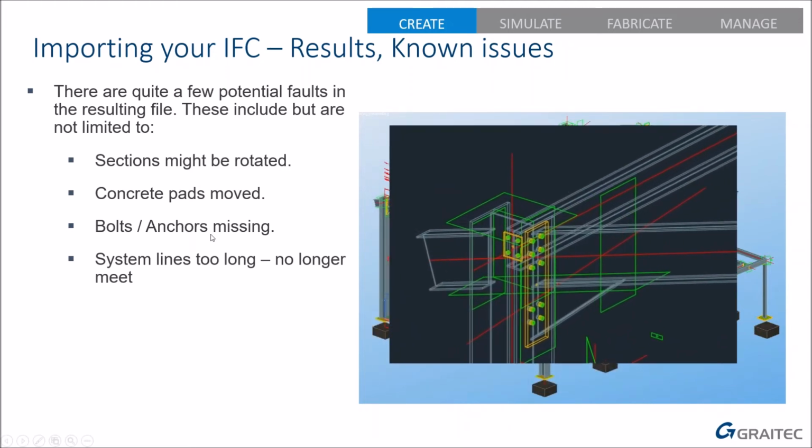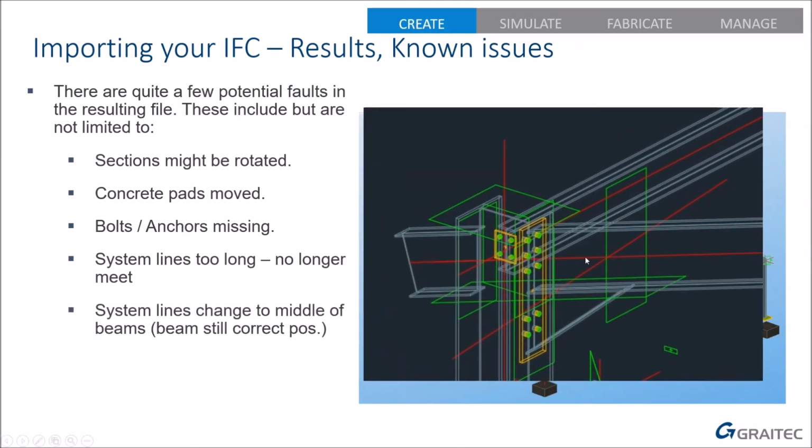And actually, if you go into 2D wireframe, you can see they've also moved the system lines. The beams are in the right place. I have checked. They're in exactly the right place, but the system line is no longer top middle for the horizontal beam or the rafter. The system line has been moved to the middle. And that's no good because when you're doing your drawing and your dimensioning, it's important to have the system lines in the right places. When you do analysis, it's critical the system lines touch. And this file would be useless on both counts.